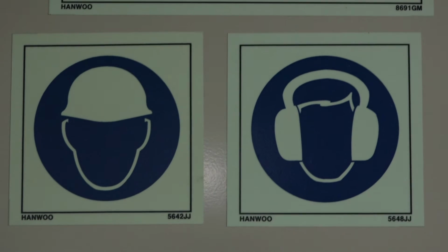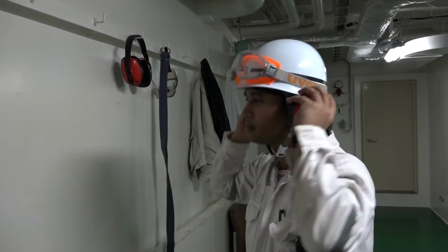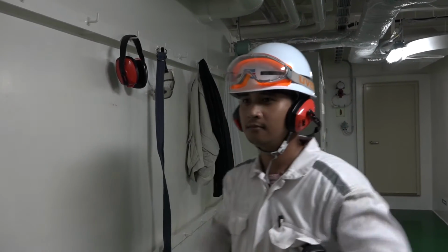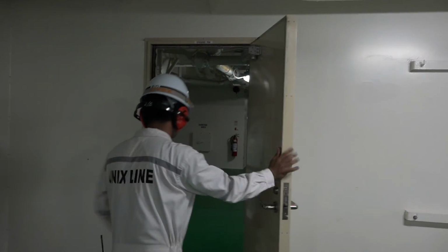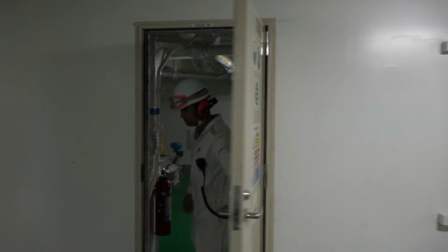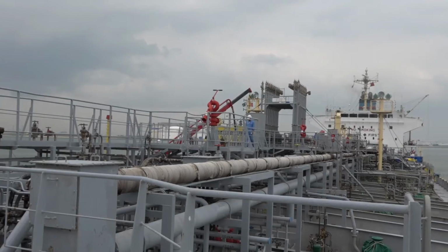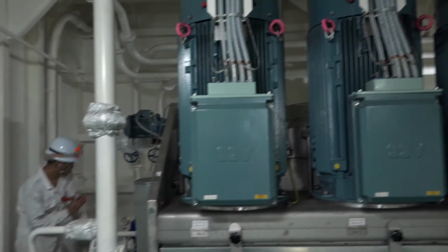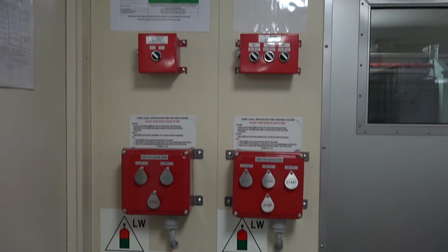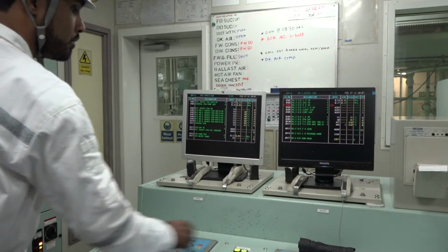Sound. Sound-related hazards include equipment noise, impact noise, and vibration. Very high sound levels or continued exposure to noisy environments are obviously hazardous to your hearing, and proper hearing protection should be used at all times. Less obvious is the influence of noise levels on communication, leading to misunderstanding and potential human error. The presence of an energy source doesn't mean a hazard exists, but the greater the energy source, the bigger the risk of potential hazards. Ranked in descending order of effectiveness, the following control measures can be used to mitigate the risks associated with any energy source.